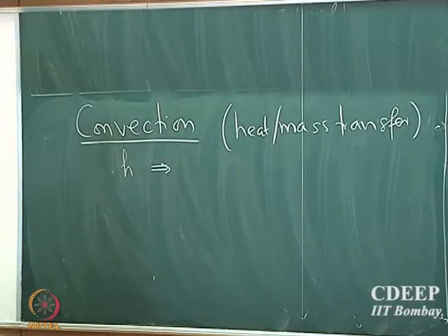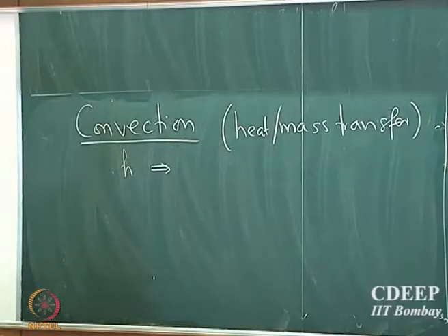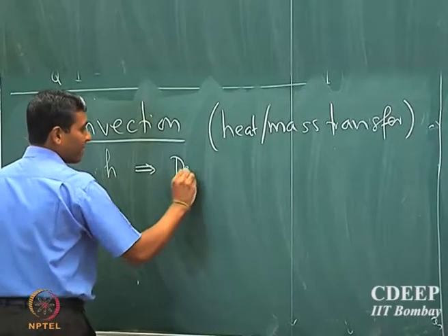So far we always assumed there is some quantity called heat transport coefficient and it is given to us. So now we are going to see how to estimate this quantity called heat transport coefficient. In fact, I mentioned before that the heat transport coefficient is not an intrinsic property like density, conductivity, etc. It is a fictitious quantity which is defined for convenience purposes.